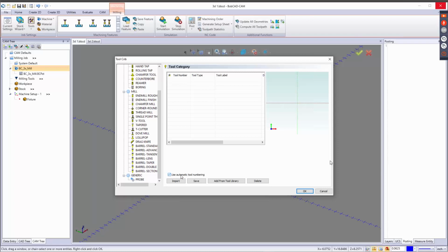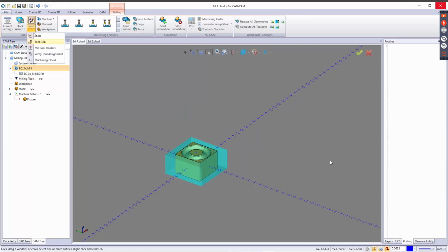Because once you start one tool path and you remember it, you got a tool crib in there that you want to use, it will not look at it anymore. So yeah, just be careful of that when you're doing that. But tool cribs are great to have. I like to use them. Especially because I don't want to modify anything in my tool library in case something happens to them. I got this tool crib I can use. And you can also send it off to somebody else too and put it in their computer also on that. So tool cribs are great to use.